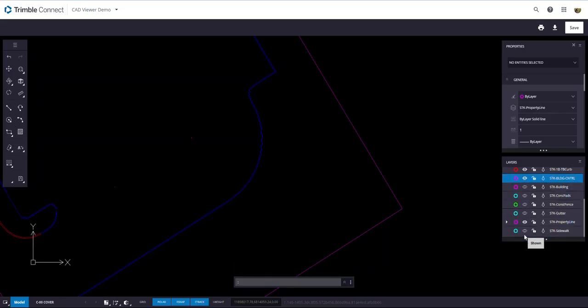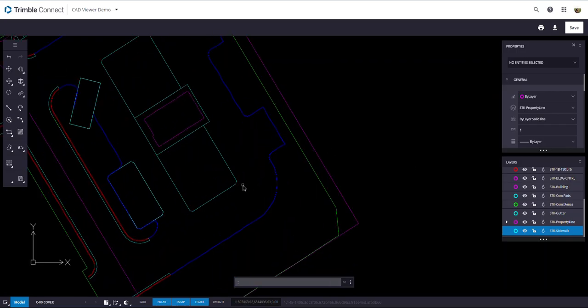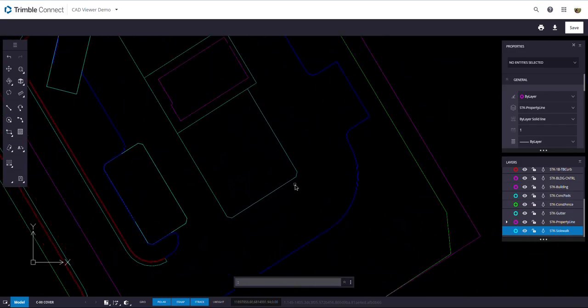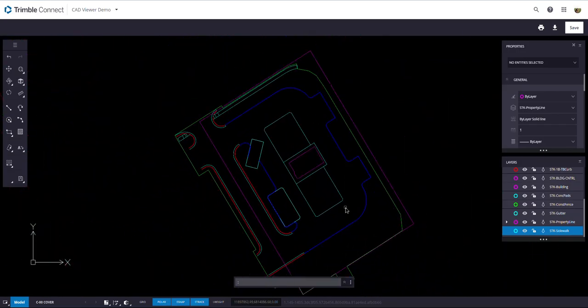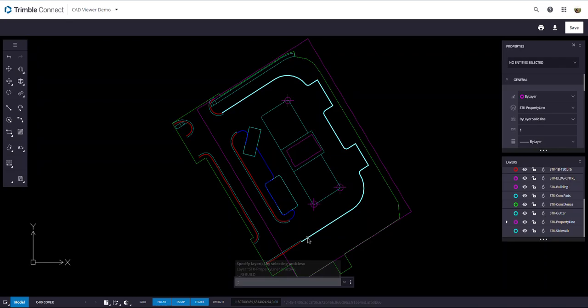So we're going to turn on all the STK because we filtered the STK out for us, right? So the points are there, and they're small. But if we zoom out and use the rebuild, you'll see now there are those control points. So that's the building canopy control points that we have. We have our line work. We're adding more and more data that we're preparing to send out to the field.